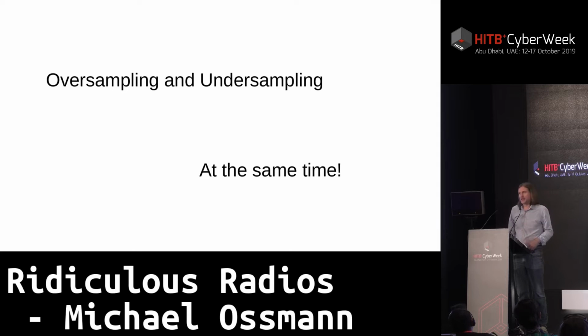But we're also undersampling, and that is that we are sampling at a frequency that is below that intermediate frequency of 44 megahertz. And so that's sometimes called bandpass sampling. But in this case, I'm calling it undersampling, because I think it's cool that it's possible to do undersampling and oversampling at the same time.